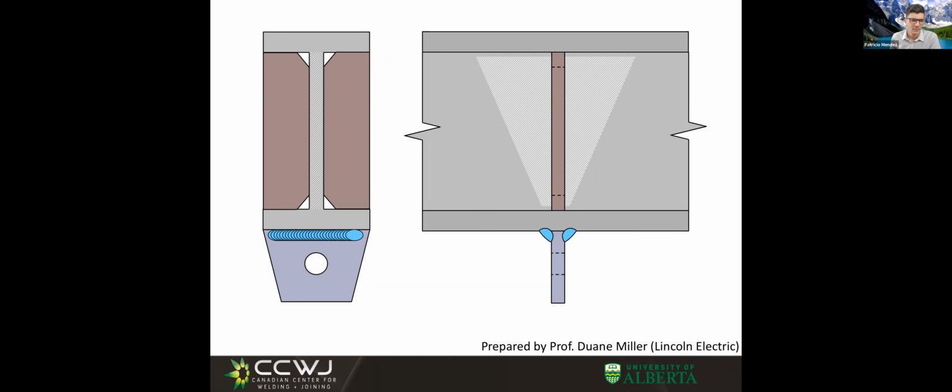Look at this, and this is pretty cool. If I really wanted to have my plate transverse to the web, I can do it. Then I would put these load transfer plates inside, and I would weld them to the flange, and I would weld them to the web. And now this is great because this plate is against the very rigidity of these other plates, right? So we made the sections transfer load in a parallel way. That's the way it was framed. But the way I see it myself is all about stiffness, right? So now the flange here is not compliant anymore. It's very stiff.